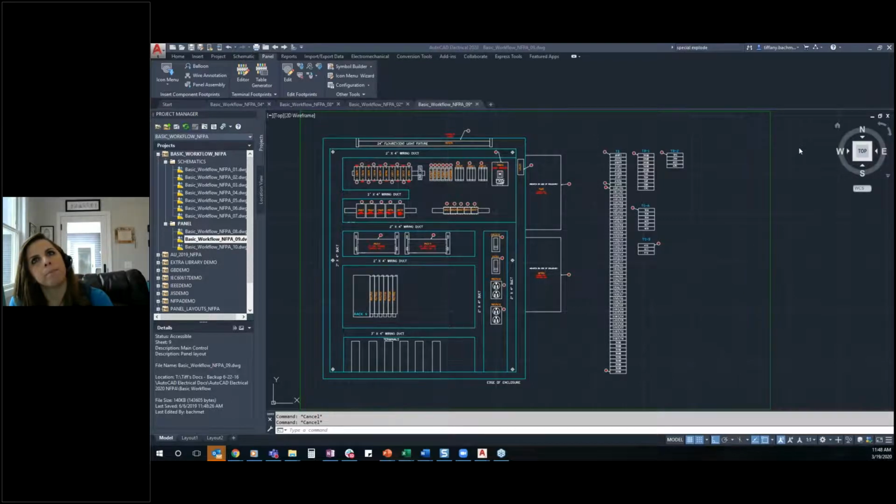Okay. The audit should catch those. You'd have to make the edits to them then, though. Yeah, then I have to essentially delete out the terminals or kick the drawing out of the project and bring it back. Then it detects that there's duplicate terminals. But then I lose all my project drawing specific data, which I then have to put back in.